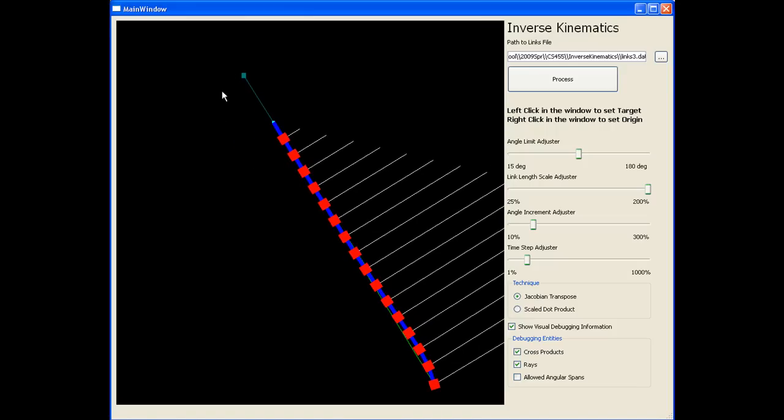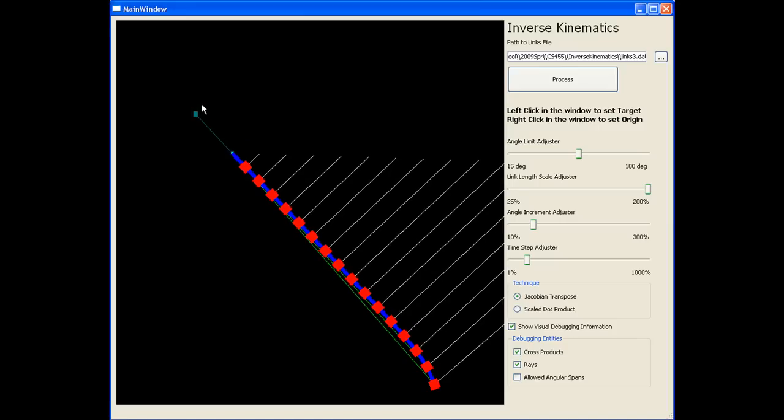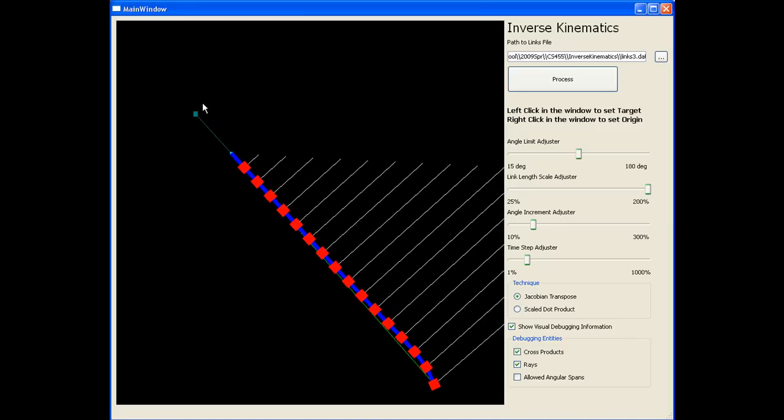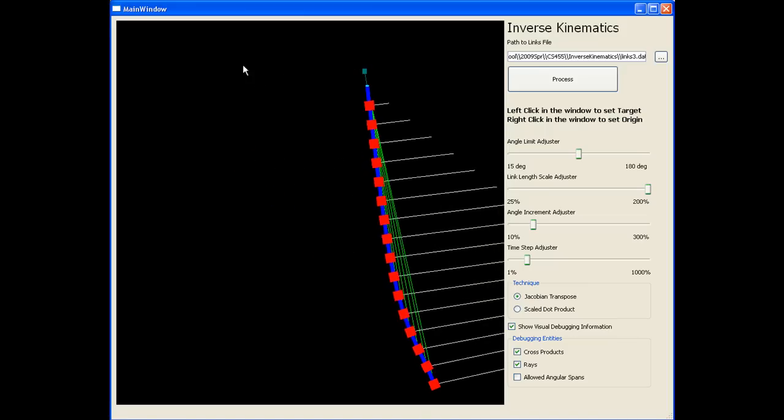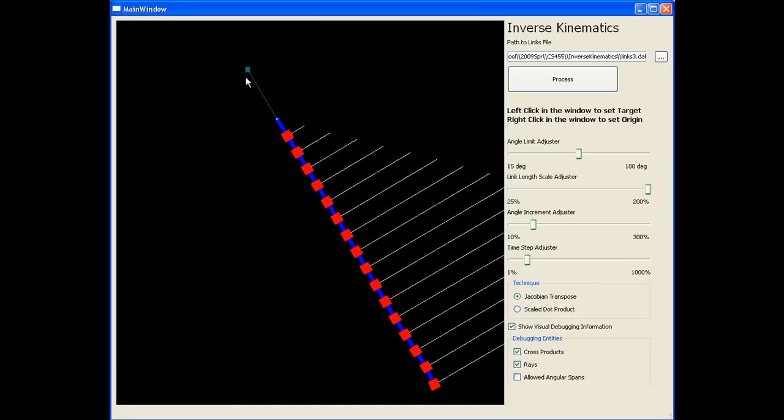This is because after using the Jacobian to solve for each time step's angular changes, each link's angular change is multiplied by an arbitrary scalar. You can imagine that if this scalar were very large, the arm would never hone in on its target because each step would be far too large. Imagine trying to move forward and step on a dot 10 feet in front of you when the only way you can move is to jump 5 blocks at a time.